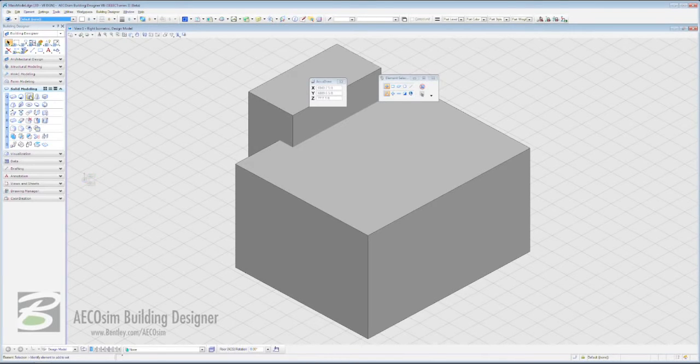To do that, we're going to come to solid modeling again, and choose cylinder solid. The cylinder solid dialog box opens. Again, we're going to choose points, AccuDraw. We're going to choose orthogonal, and we are going to offset it. So we're going to come down here. The little yellow X in the icon, by the way, is called AccuSnap. It works in concert with AccuDraw, and it's going to be one of your most powerful utility friends in Building Designer. So we're going to press the O to offset again.